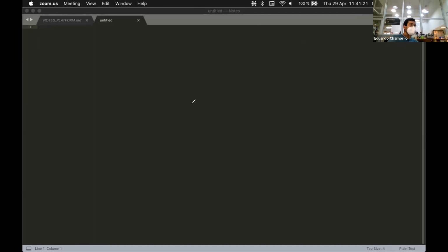So that's it. We have 2 cases then. Both the boards are powered at the same voltage, and then the communication happens at 5 volts. Or we could have 5 volts and 3.3, or whatever. And you need a level shifter, and you also need to take care of the powering of each of them. That is more into the field of electronics design, but it also applies, or it's needed in the level 15.